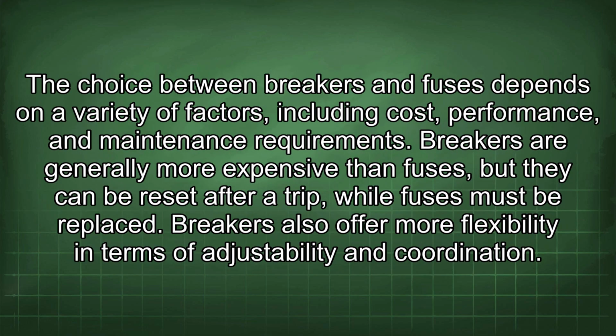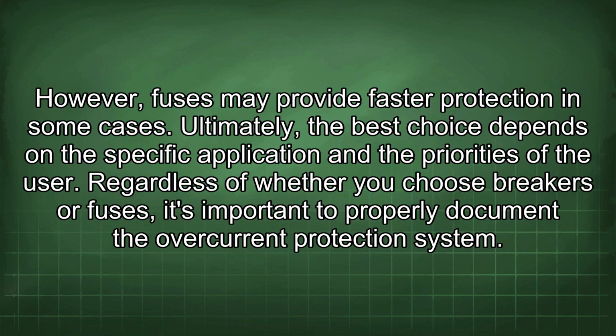The choice between breakers and fuses depends on a variety of factors, including cost, performance, and maintenance requirements. Breakers are generally more expensive than fuses, but they can be reset after a trip, while fuses must be replaced. Breakers also offer more flexibility in terms of adjustability and coordination. However, fuses may provide faster protection in some cases. Ultimately, the best choice depends on the specific application and the priorities of the user.